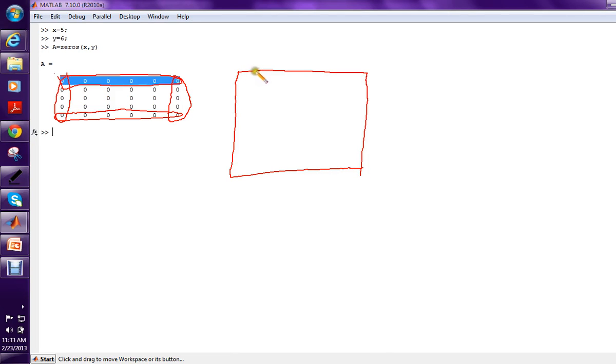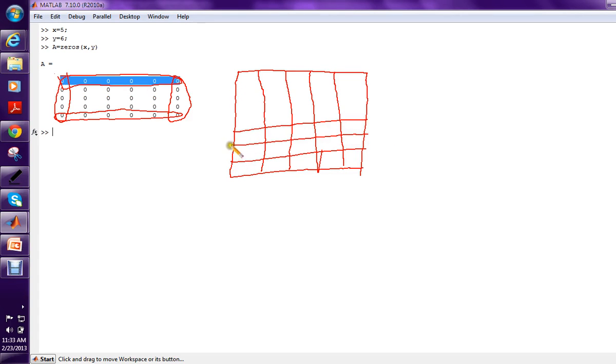along the x-axis we have divided into 5 segments. So 1 2 3 4 and 5. Yeah, 0 1 2 3 4 5. And on the y-axis it should be 1 2 3 4 5 and 6. Say something like that. This is the domain, right? And what are the boundary values here? So these points are boundary values. These points are boundary values. These are the boundaries. So we have to fix the boundary condition here, right sir? Okay, and only these values are unknown values to be determined, because these are given to us. So we have determined our matrix.